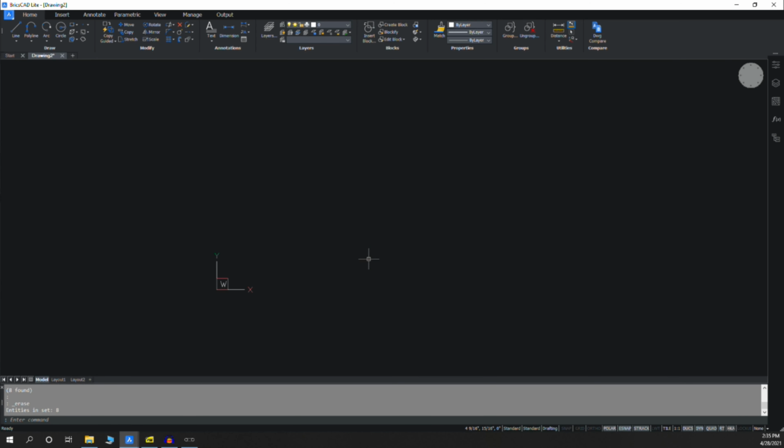Roof pitch in the United States is described in terms of number of inches of rise per 12 inches of run. So common roof pitches are like a 6 pitch. You can buy standardized trusses in pitches up to like an 8-12. But if you want anything really steep like a 12-12, like you might see on a Cape Cod, you'll have to have those custom ordered. And really, getting trusses custom ordered is not a big deal. They're not that much more expensive from a custom truss manufacturer. You'll just have to wait a lead time, so take that into account with your build schedule.